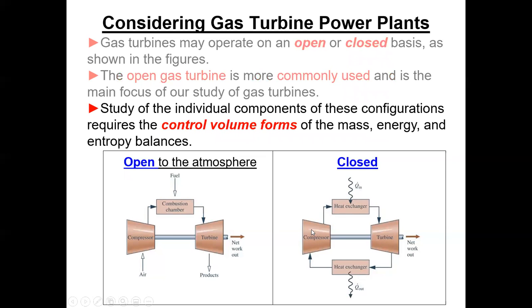Now on the closed cycle, instead of considering the combustion, we say we'll do that combustion someplace else and worry about it another day, and we'll show this energy input as a heat exchanger with some nice Q dot in that we're putting in. Likewise, to close the cycle, we have to assume that these products eventually come to the same temperature as the air.